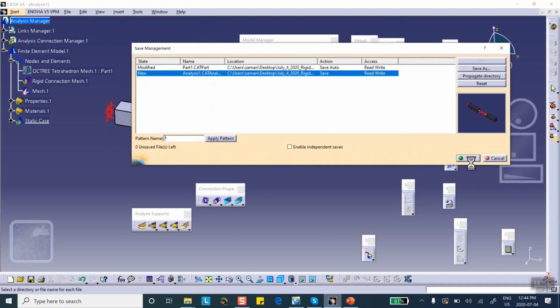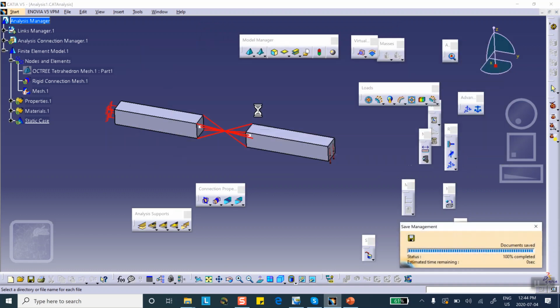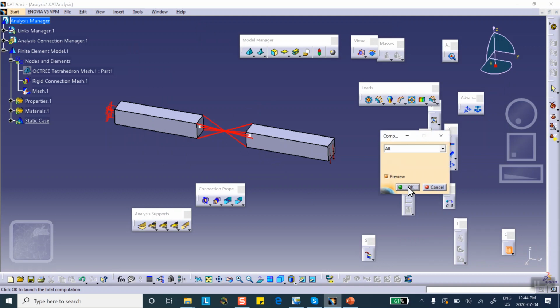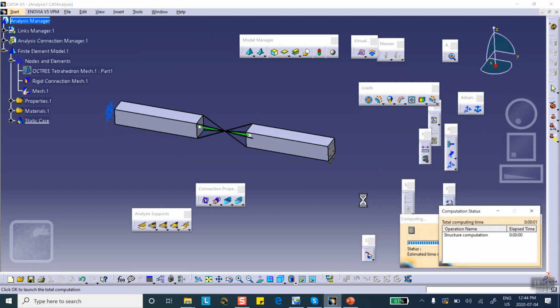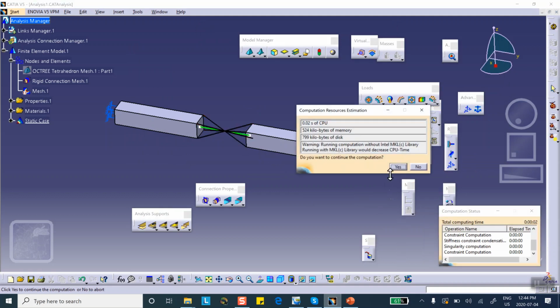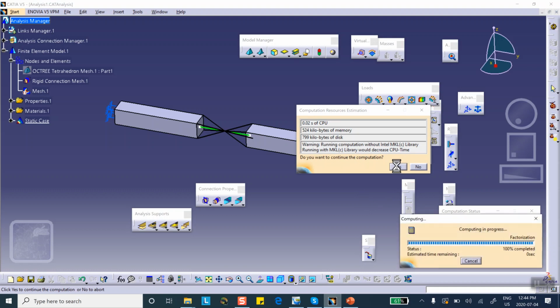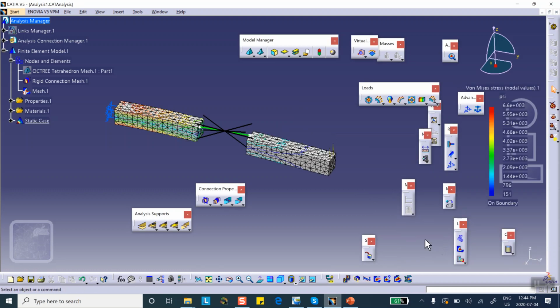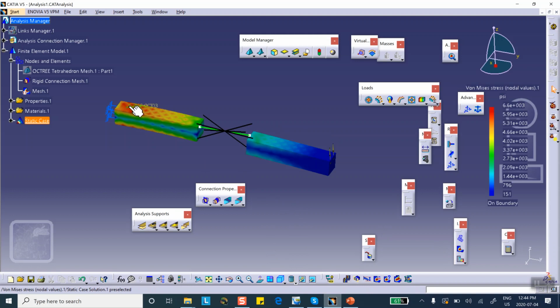Okay. And we're going to run it. Nothing unexpected is going to happen. This beam is going to bend. You can see there's the deformation, stresses. Biggest stress at the clamp, and the stresses gradually decrease, because that's where the biggest moment is, by the way.